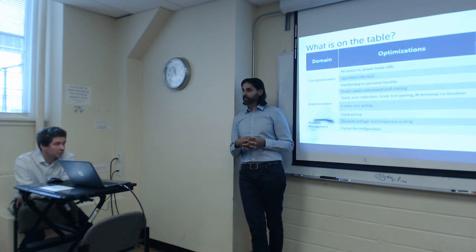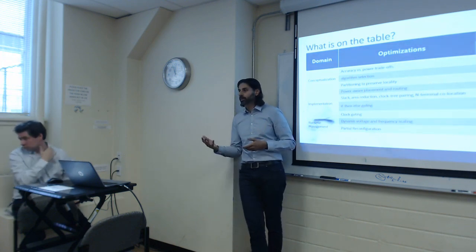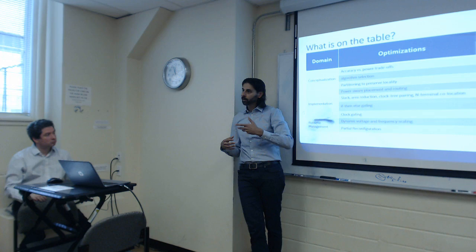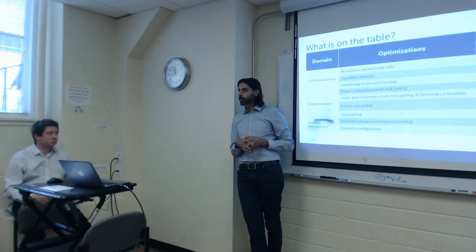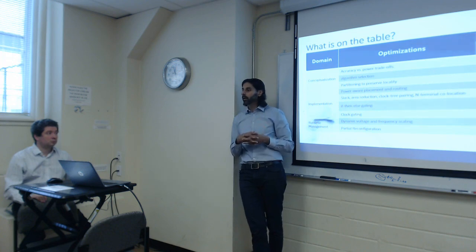If you enter unreasonable clock frequencies and utilization, you're going to get garbage out. Garbage in, garbage out. But if you use a flow where you compile your design through Quartus and export a profile that you can enter into the EPE, with perfect information, in our benchmarking, we see about 15% difference between the two.